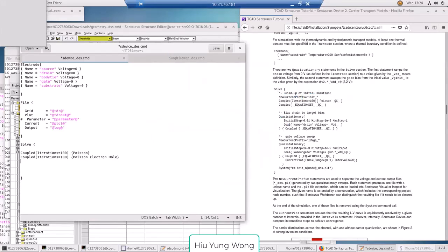Okay. Now, after this, we are doing this thing, a little bit complicated. I still want you to copy. This is called ramping now. Now you tell the computer to solve it. Please do quasi-stationary. Let's just copy it with the brace. Initial step equal to 0.01. Minimum step equal to 1e-5. Max step equals 1.